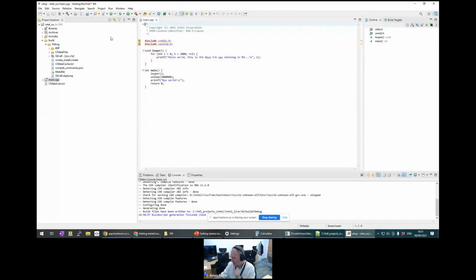What we want to do then is we need to create a simple application. Now we need to download the processor soft file into the Agilex device. In the interest of time, I've already done that, so it's already running on this Agilex. But we can do that using the soft file from the Quartus programmer.